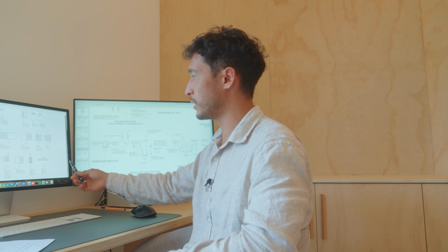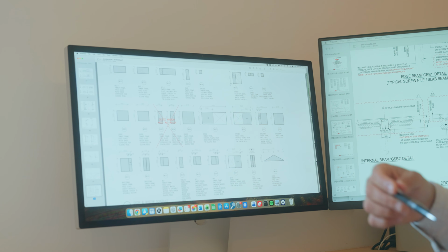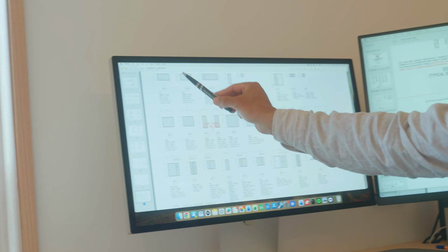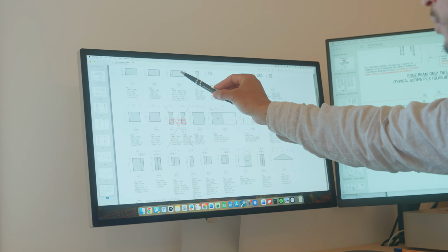The next set of documents we need is a window schedule. Now, a lot of people don't really know this, but it usually takes up around 10% of your budget for windows and doors, so it's really important to try and get as much accuracy as possible, particularly the variance between, say, hardwood double glazed windows versus aluminium standard double glazed windows or thermally broken windows. There's significant variance between those prices. So it's about understanding how many windows there are, what the layout is, because a fixed window is going to be a lot more expensive.